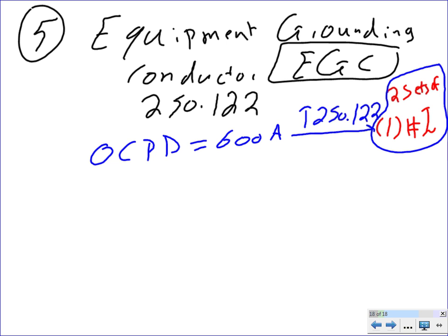This is very important, guys. Equipment grounding conductor goes with every set. The same size goes with every set. So if I parallel, DJ, 15 sets, how many of these conductors have to go? 15. Yeah, that's an easy one. 15 sets. Any question, guys? 1 with every set.